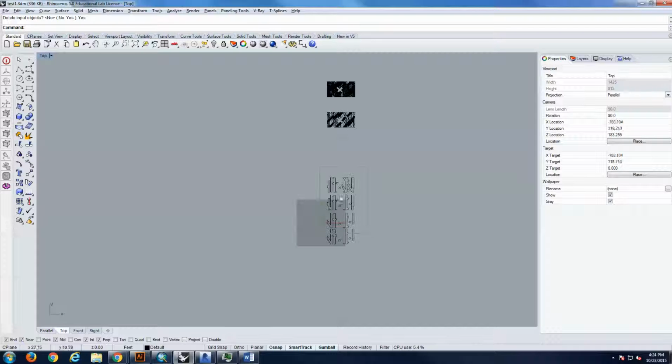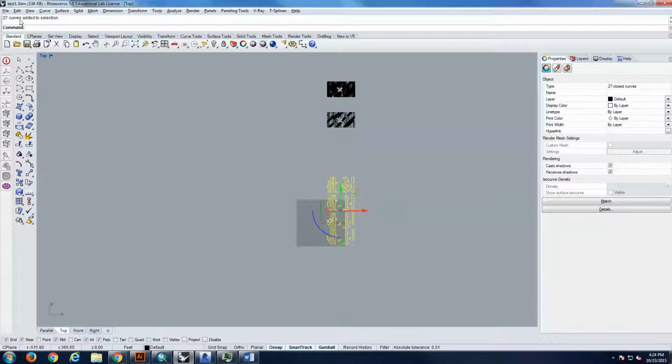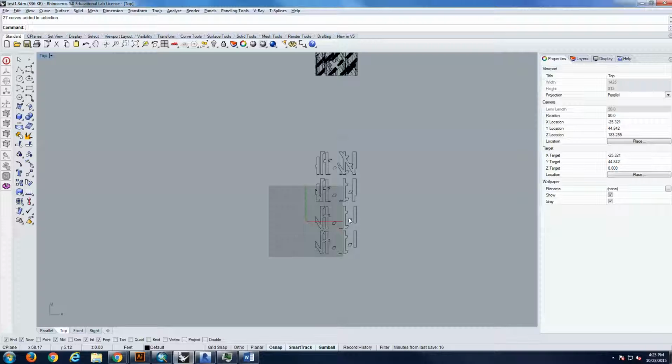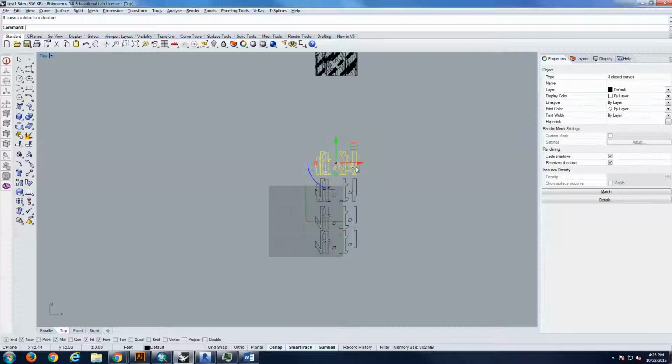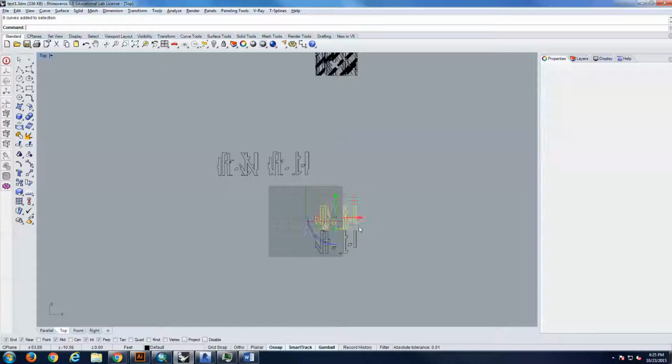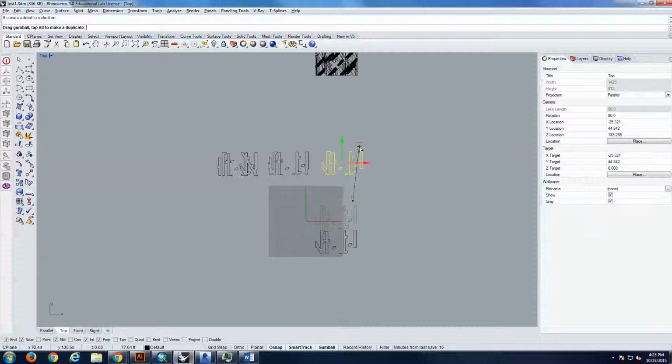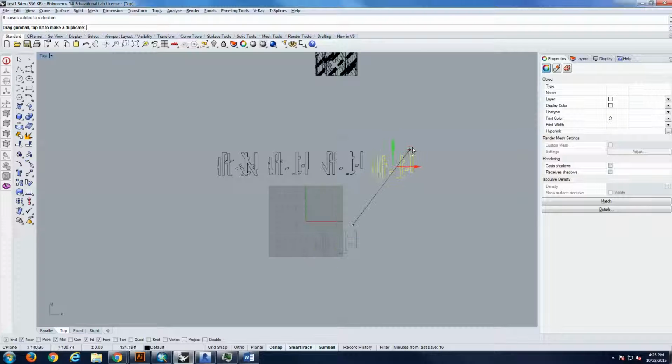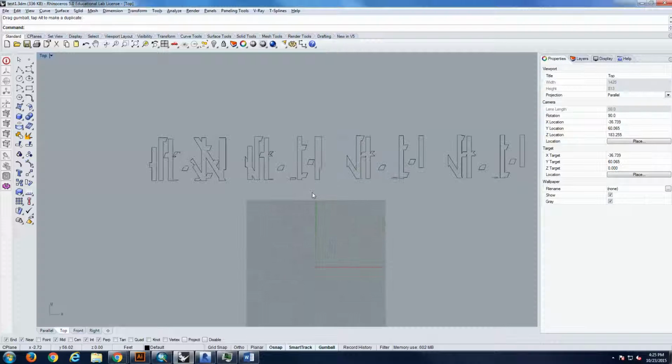And you can go to the top view and you can export it as Illustrator, or you can place them in a template from Rhino. Okay, so these elements should be placed, obviously organized, one after the other, so you know exactly the condition of how they should be glued afterwards, no? Otherwise you're going to lose track of it, especially with very complex projects, no?